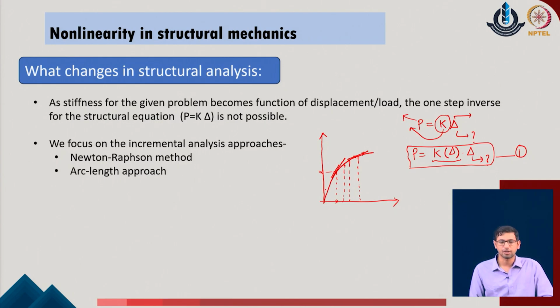So, there are standard incremental approaches which keep on incrementing, say, on the load value. With the increase in the load value, we obtain the particular point at which we are trying to evaluate the displacement, and for that particular point we also cross check whether the stiffness parameter, which is continuously being modified, is giving us the correct response.